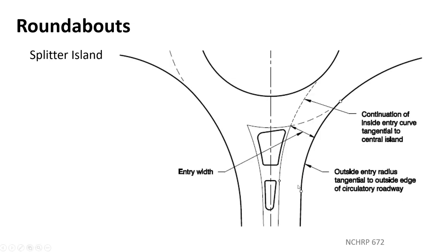On this actual lane coming in, this is how we would normally design this coming in. You can see down here we've got these circle points, or where the radii start and end, or where the curves start and end. And so for the edge of pavement we come in, this is where that curve would start. Here is where this curve ends, and it's probably a point of compound curvature, and it's going to move into this next curve through that. We're going to see some examples of that coming up here in a second.